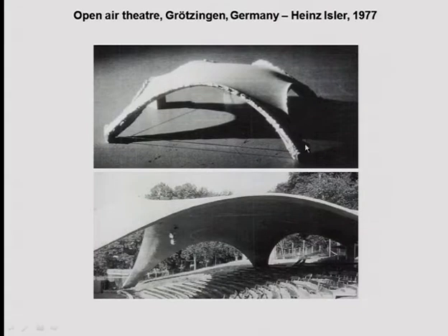But how do you get this model? Of course, you can discretize it in a set of catenaries, but you can also do another thing. You can hang a piece of fabric, make sure there is proper dead load on it, and then you freeze it. And that's the shape you get.